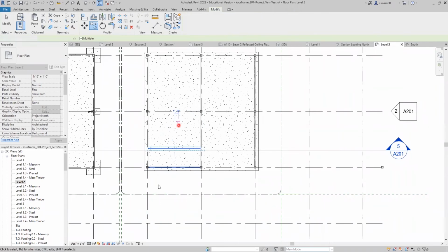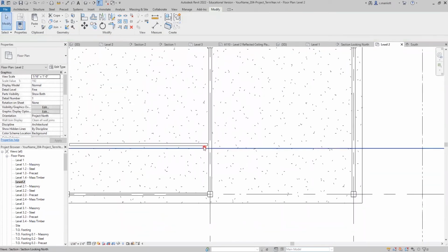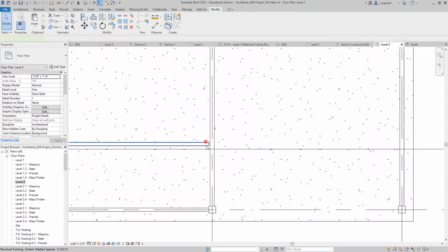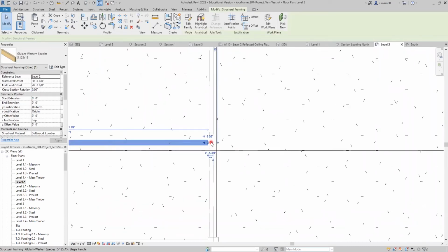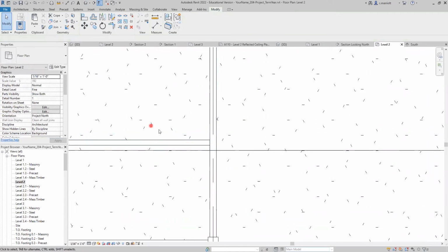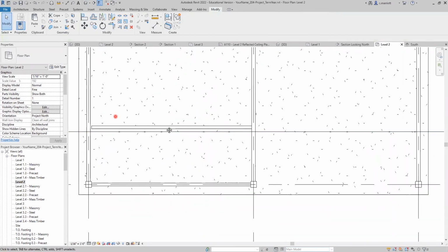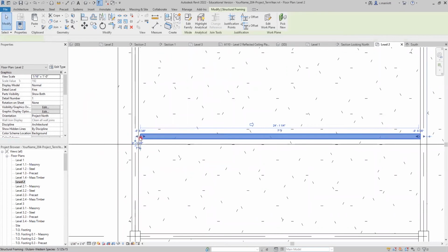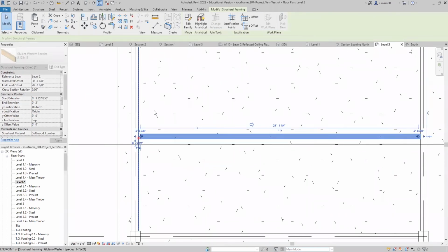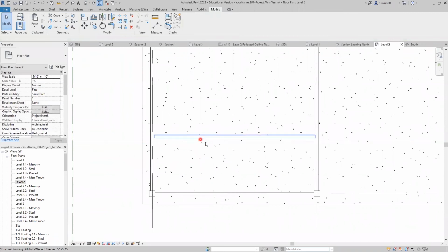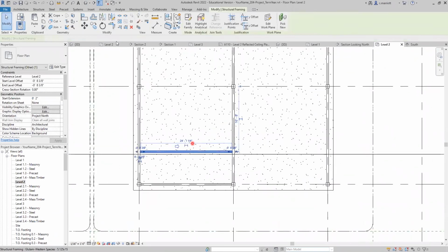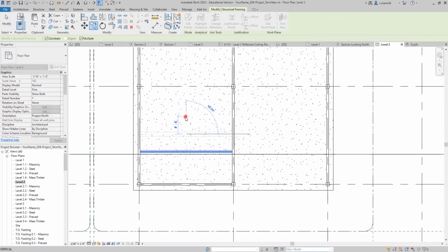Spacing for these is going to be 8 feet 4 inches, which is a little different than what we've used for our other spacings. But the reason for this is the cross laminated timber flooring that we're going to be bringing in. So you can see I had to stretch it because the girders are a slightly different dimension than the columns. Okay, so I'll go ahead and continue with these two copies, but I need to be careful which ones I copy where.